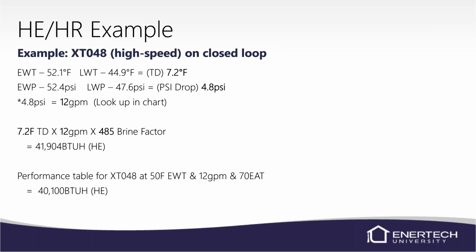So we're seeing how the performance is without even looking at the refrigerant pressures. Normally, we're not going to be above, unless maybe your flow is off. Maybe you're not really moving 12 GPM, maybe you're moving 11 or something like that. As long as we're within 10% plus or minus of what's in the manual, then we're okay.